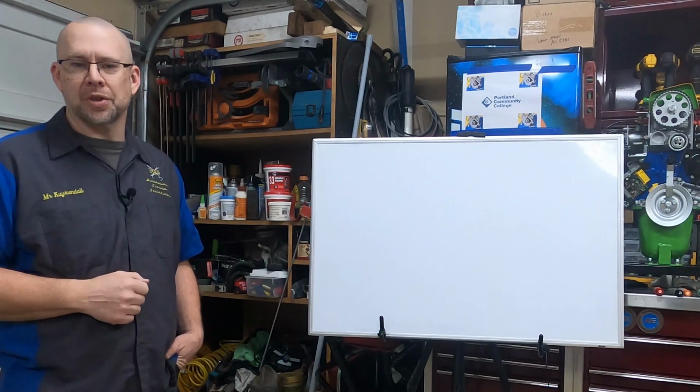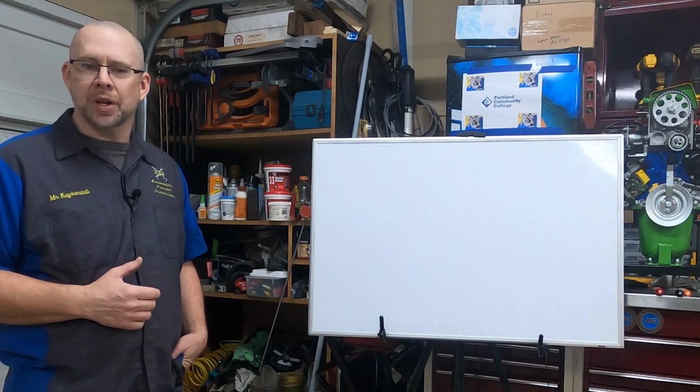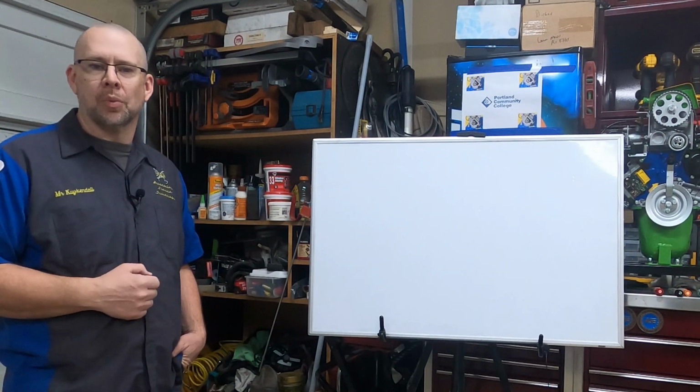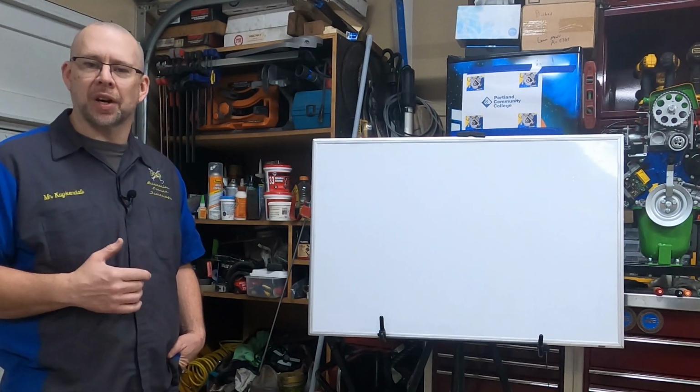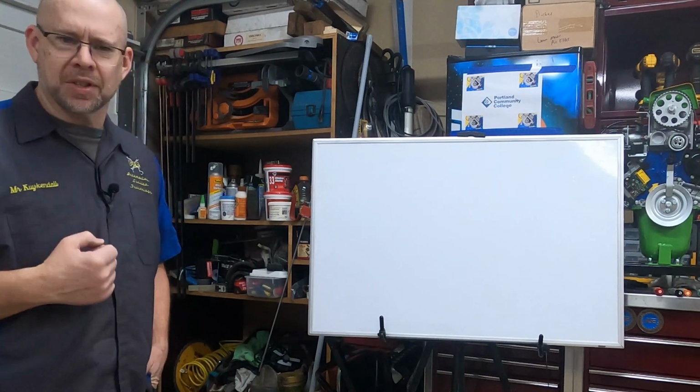In a more modern version of this system, there'll be a cam and crank position sensor acting as a trigger. Their input will feed the powertrain control module, PCM, which will then decide when it wants the spark plug to fire based on various other conditions. A little diagram of what that might look like could be something like this.